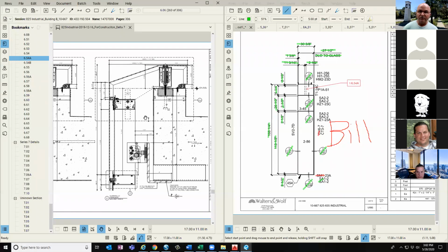My validation of units is from a different frame of mind than building the unit. I really want to mathematically prove that this unit is absolutely correct, and I'm going to use the shop drawings and a calculator for the most part to determine that. If I have to rely on the BIM of the unit, that's almost just making sure that what you built doesn't have any clashes. But realistically, I need to prove that mathematically and not visually.